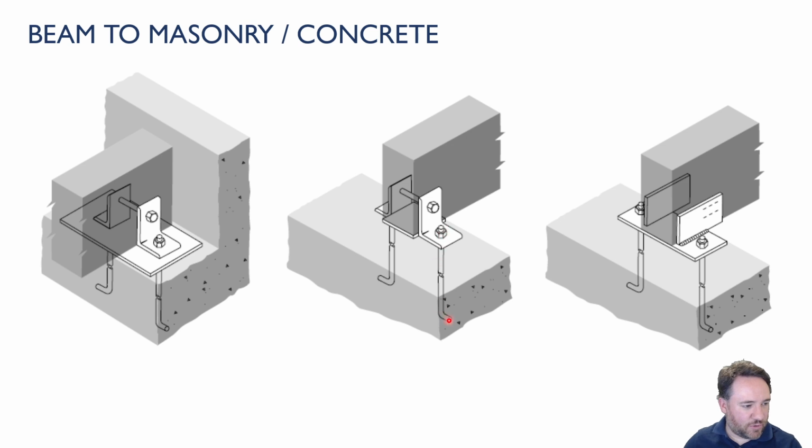And I have some bolts cast into the concrete, or if I don't cast these in, that's fine. I could also use adhesive anchors to connect down to the concrete. The one on the right here, these little lines here, this is indications for timber rivets. So you can see that the line directions are in the same direction as the grain of the beam that's sitting on top. So this is just an alternate situation for if I have timber rivets instead of using bolts here, for example.